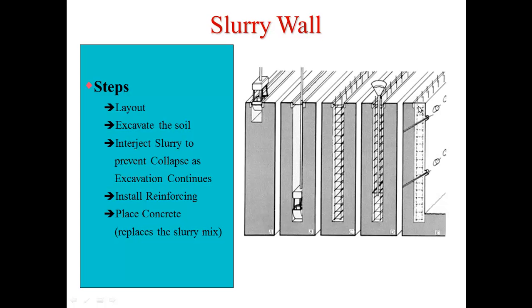So once they're done, then you can see they've got these tiebacks going in to kind of hold it into the soils. They'll excavate this side of the building site, and they end up with their foundation wall put in place, so you could have a building within feet of this area, and they're able to put these tiebacks in and the cured concrete. So it's basically pouring your concrete wall and then doing your excavation after the fact.